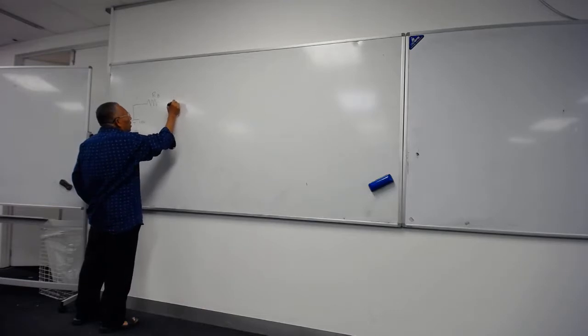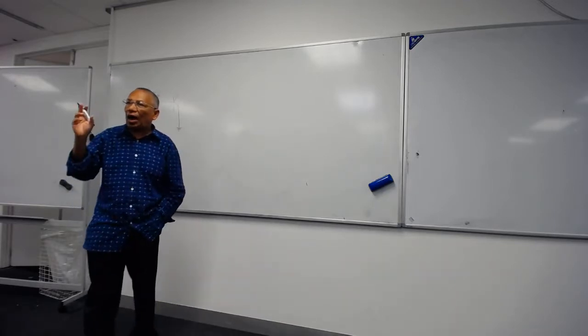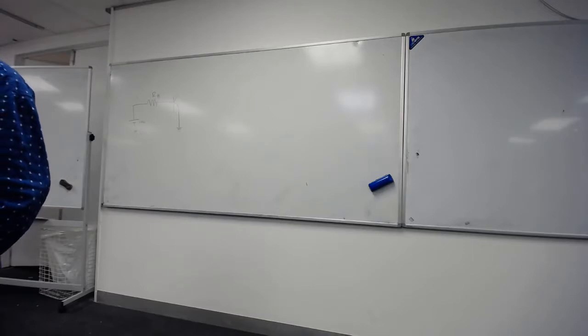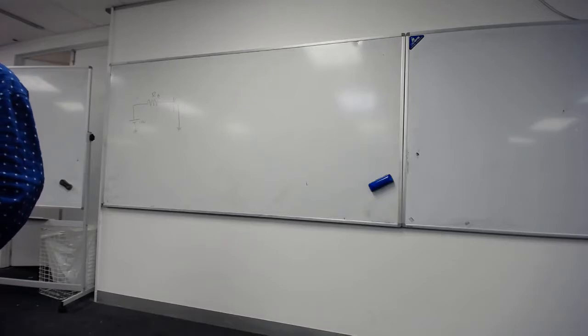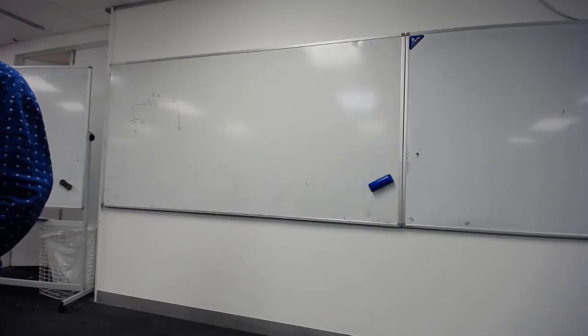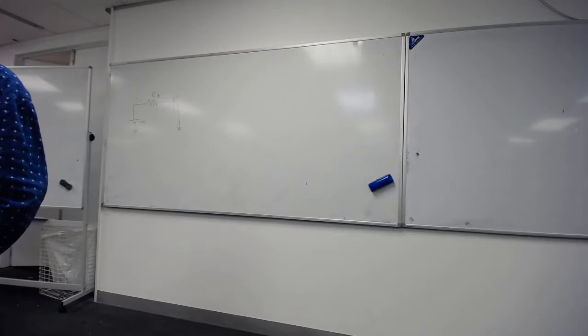And then we have a transistor, and as we have discussed in the lab and elsewhere, the beta is a characteristic of the device. Beta never changes. What is the difference between beta and GM? As far as the characteristics are concerned, beta is a characteristic of the device. Once you fabricate the transistor, the beta will not change, unless you actually heat it up or really destroy it, do something to it that it doesn't really like at all. Then you will have changed this beta, and you won't be able to use it much.